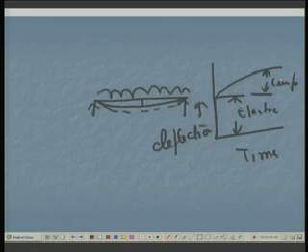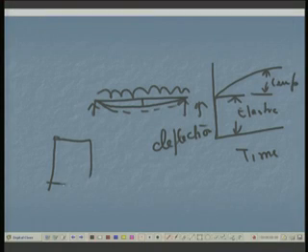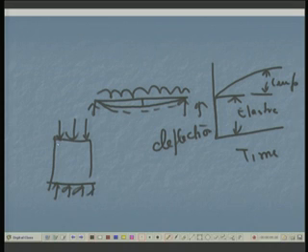That means, with time, even though you have not increased the load, its deflection increases in the case of a beam, and strain increases in the case of a loaded cube specimen. You just keep the load. Initially it might have deformed just this much, but this deformation will go on increasing with time. So, deformation increases with time, and this phenomenon is known as creep.